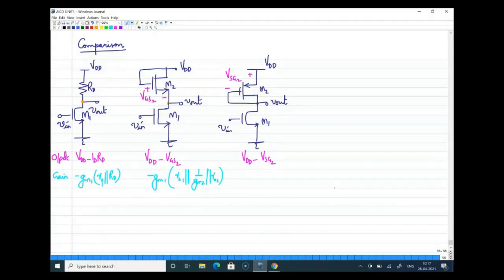And the gain remains the same. So I'll just put it is same as the previous. No difference. Now we also saw a modified version of this, but basically why we went for modification is to have a smaller overdrive voltage, or to have a larger output swing. So that circuit I'm not bringing in here because, for practical reasons, that ideal current source should be realized using a transistor itself. Then how ideal that practical current source is depends on that only, we can talk about the overdrive voltage ratios and other things. So I'm not bringing that circuit here.